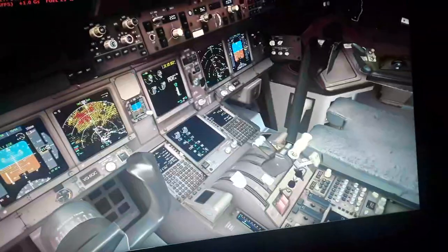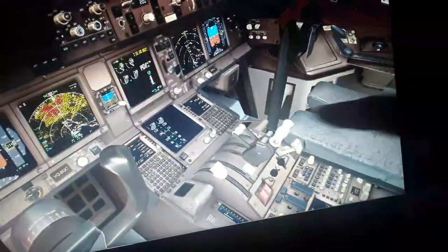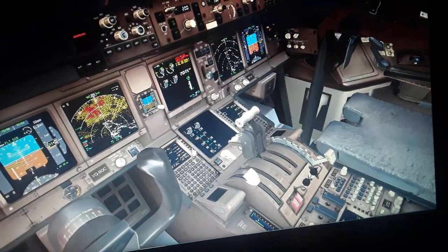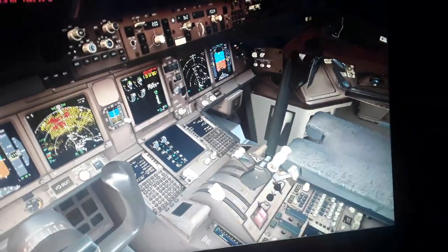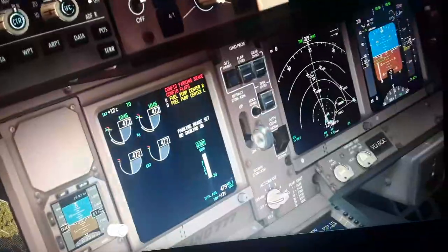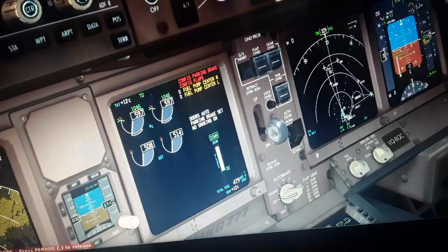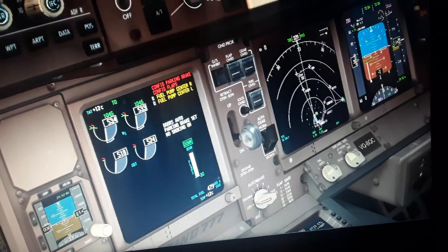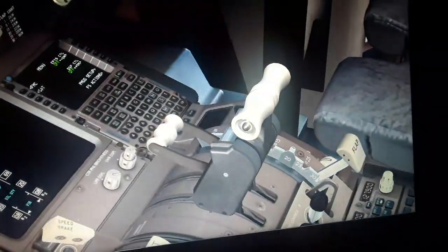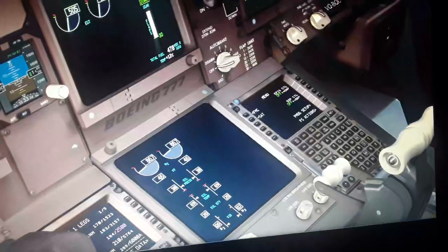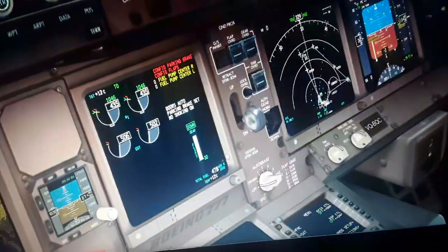With the airspeed select knob, we can set also the thrust levers for the airspeed by moving the thrust levers forward enough. You will see the airspeed commanded here, the thrust actually. For the thrust rating, you can see it takes a couple of seconds for the engines to spool up or spool down from the actual to the commanded target thrust.